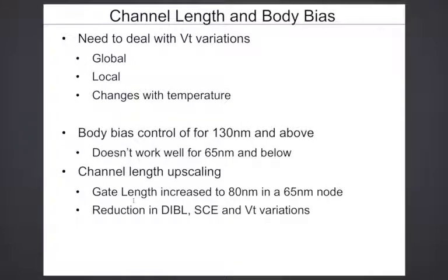So first, let's look at one very important sizing related aspect, which has an influence on the kind of variations you see in the transistor's threshold voltage. Because if you recall from the last class, it's the variations in the threshold voltage which limit how low a voltage you can scale from a practical perspective, right? It basically prevents you from scaling too low.